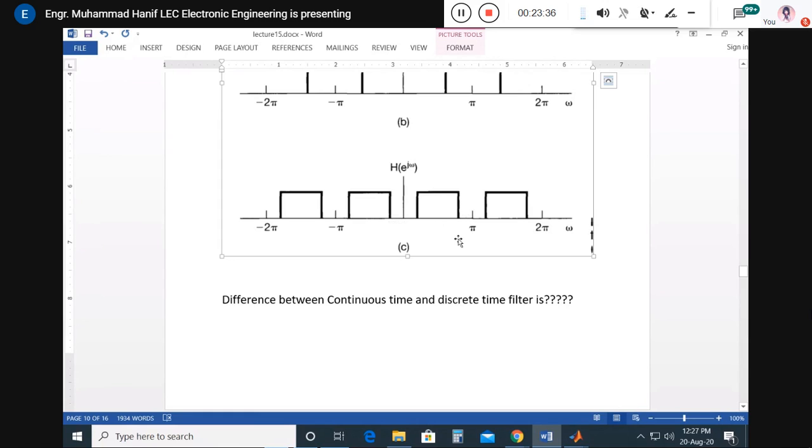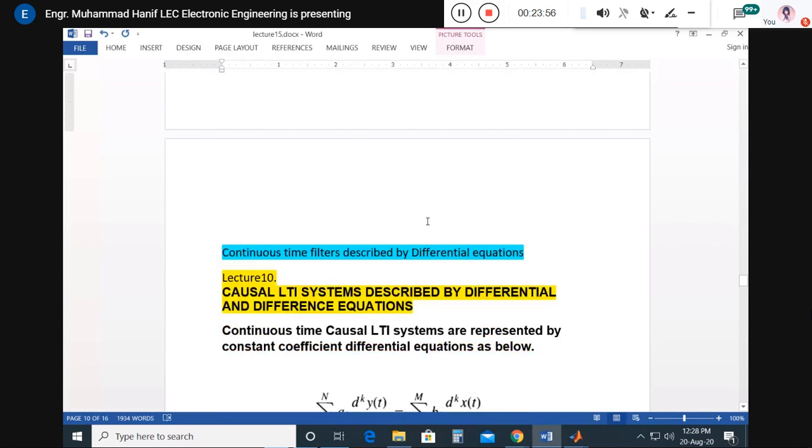That will represent a band reject filter, because it will allow the lower frequencies around 0, and it will also allow the higher frequencies around pi. In between, the portion of frequencies that forms, those set of frequencies will be rejected, and that will be defined as a band reject filter.